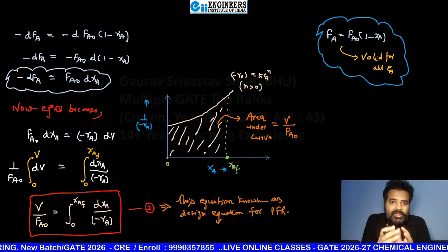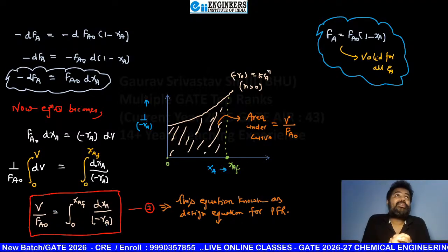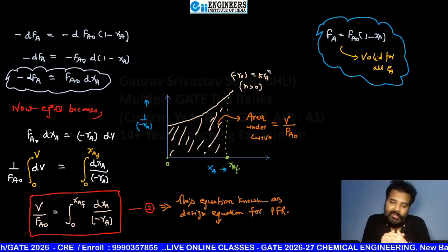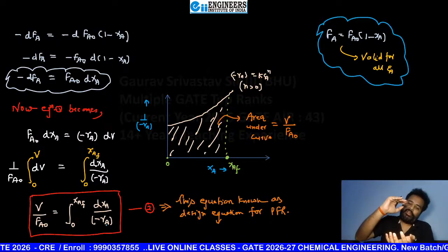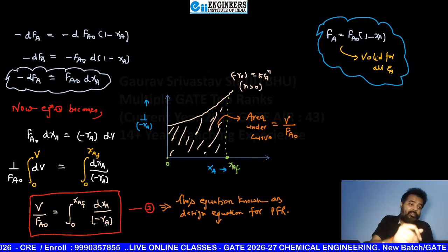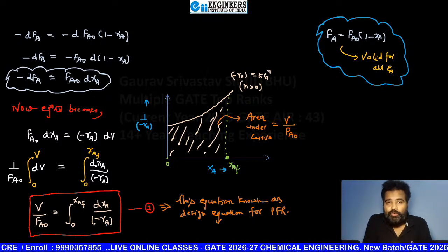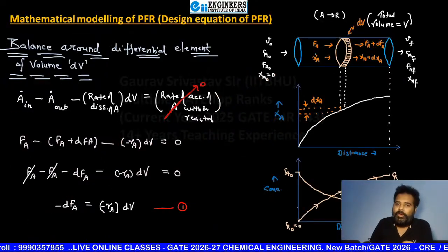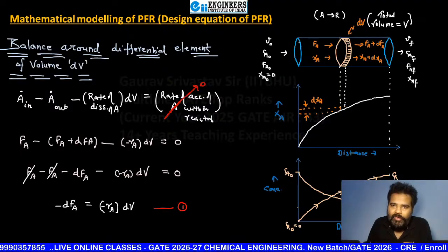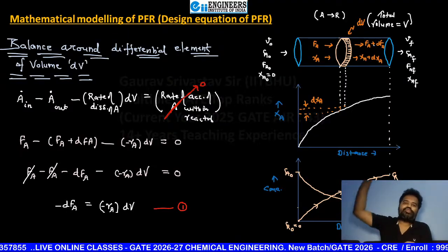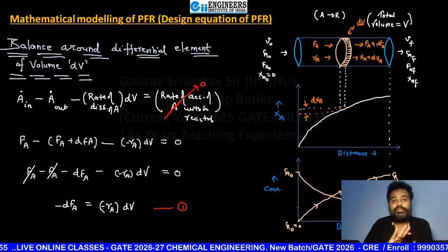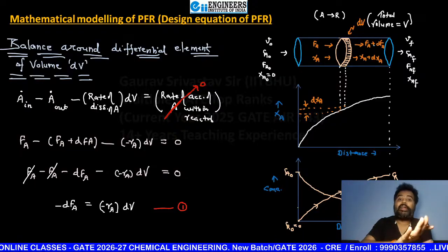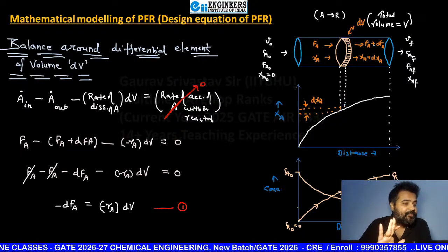So in a batch reactor, the actual thing is the volume of reaction mixture, because that is simply a closed batch reactor. If some moles are going to form there, then they can give a little bit more reaction mixture volume. So that's why there we don't take the volume of the reactor, because in flow, see, if this is in flow, no part of this pipe can be empty. But a batch reactor, any size you can make, because this is not a continuous reactor. Any size you can make, because nothing in, nothing out during reaction. CSTR also, in and out every time is going to happen. Okay, is it clear, beta Ayush?